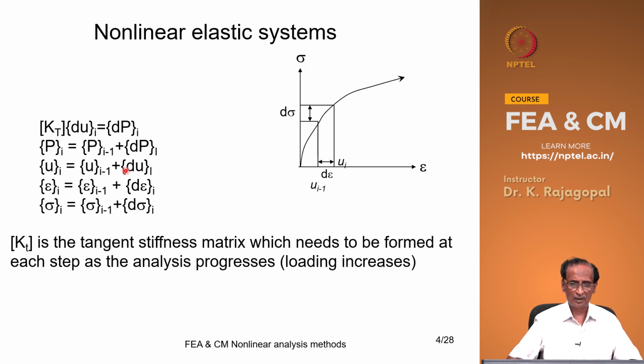Then slightly more complicated are these nonlinear elastic systems, and the simplest approach is to go in an incremental form, applying the force or displacement in small increments, so that you can follow this stress strain path as closely as possible.